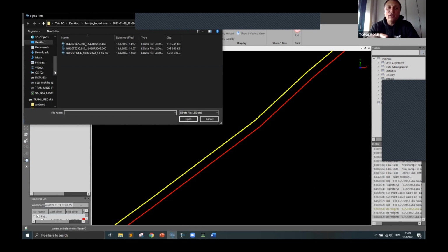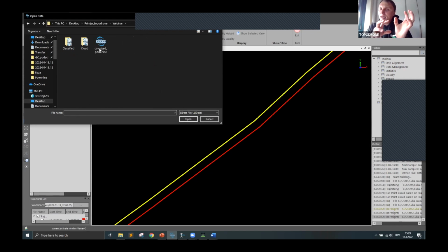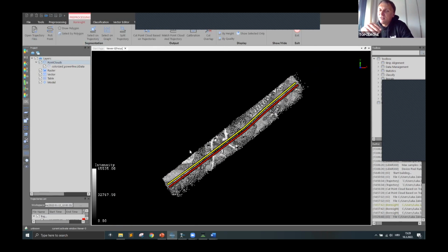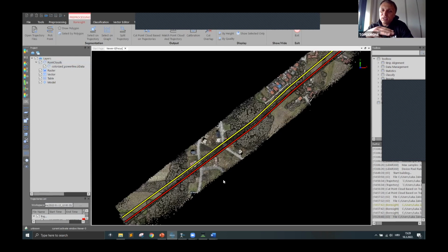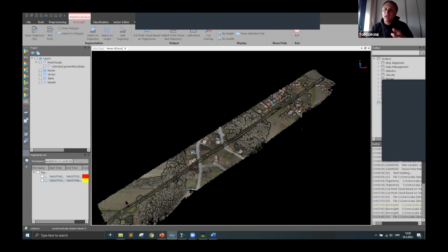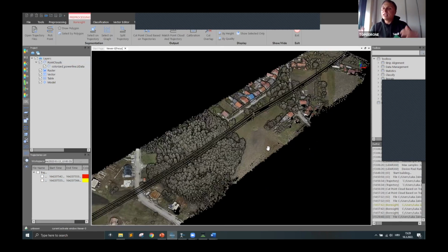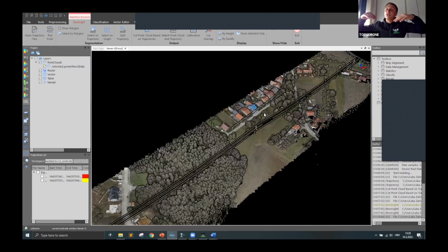While you're opening the point cloud, I would say that it's possible to colorize a point cloud, and it's a great advantage that we have a separate camera which can be pointed at a different angle. For example, if you need to colorize towers and some power line infrastructure, it's better to make a survey with an oblique flight.